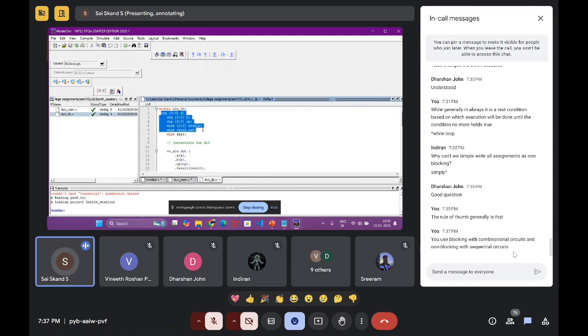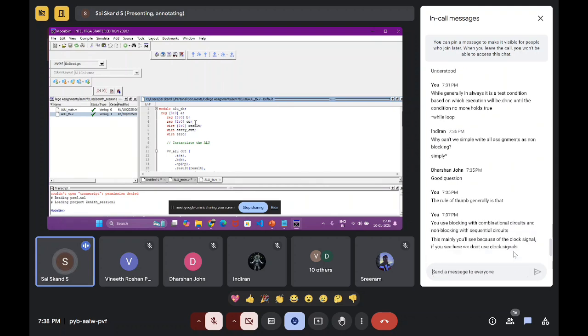Now you notice what we have done: the inputs that we gave there, we have declared here as reg. I guess you are all clear with this. 4-bit value, 3-bit value, again 4-bit value. So the results and the inputs are 4-bit and the select values are 3 bits. But why have we kept the inputs as reg? The reason is that these inputs are under this block, we are the ones who are going to control them. So we need to set them as reg, because we need to store those input values inside.